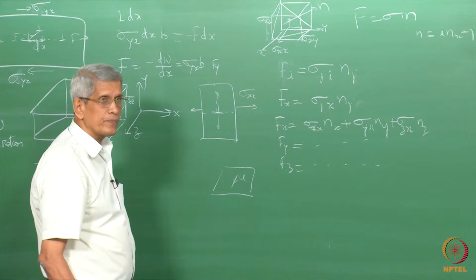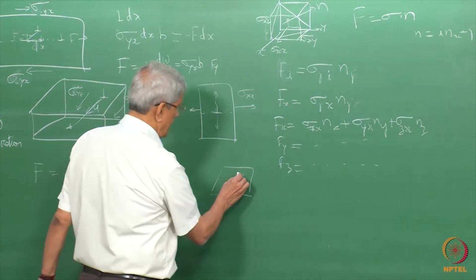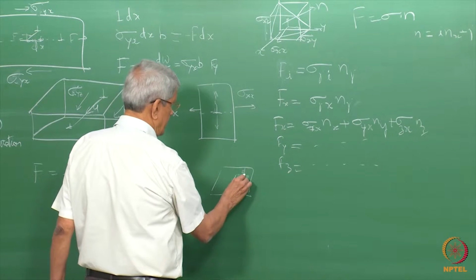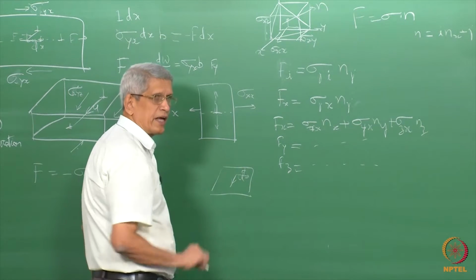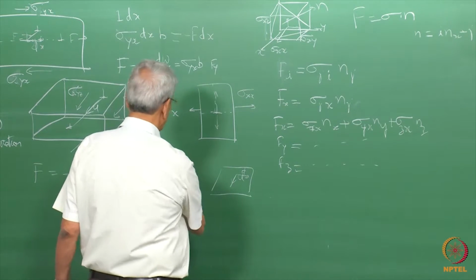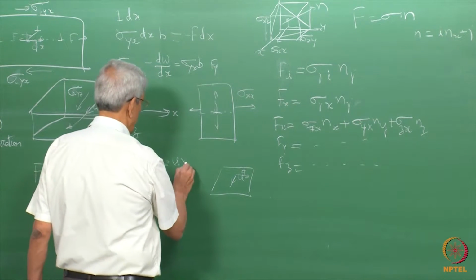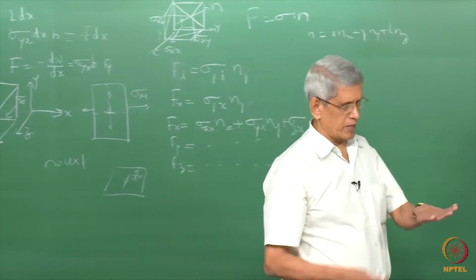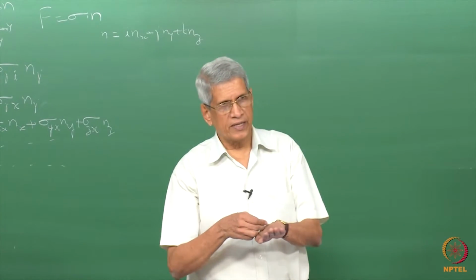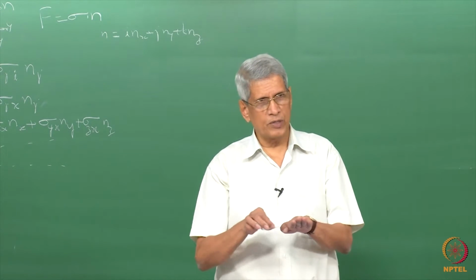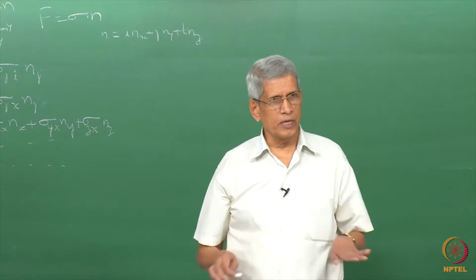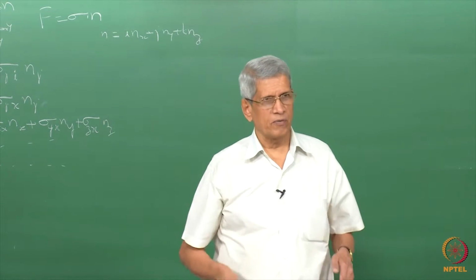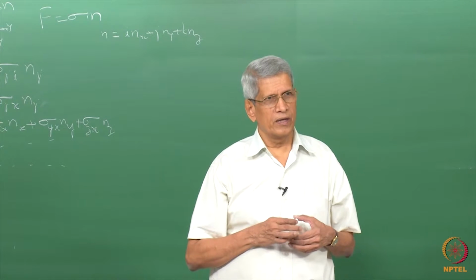And if the dislocation moves by a distance in the direction d, that is a unit vector in the direction of motion, then n will be equal to u cross d, the plane normal, because in the plane the dislocation line direction and the direction in which the dislocation moves, if you take them to be unit vectors, then the cross product will tell you the plane.